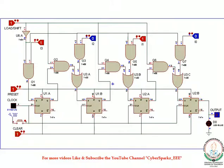Now let's start the PISO operation. We are going to input the data 1001. Upon setting the input data, you have to do the operation in load mode. The load mode will write the data into the flip-flops. So make it 0 and apply a clock pulse.